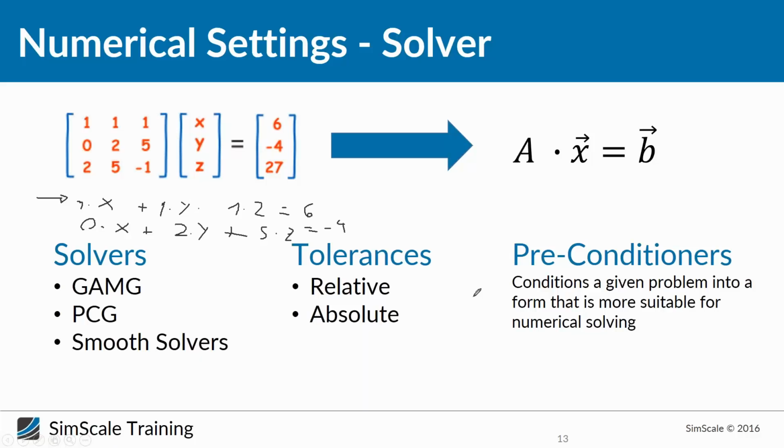And in the end, this step solving, and that is the first thing which is important for you when setting up your CFD simulation, is to choose the right method to calculate x, y, and z. From school, you may know very easy equation systems which you can solve using this Gaussian approach, where you try to get it into this special style of matrix, and then you can solve very easily. Just imagine the matrix would look like this.